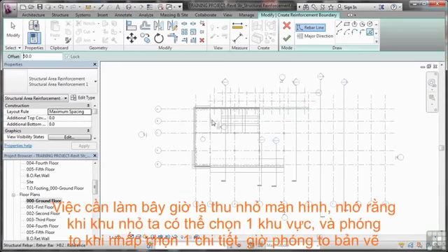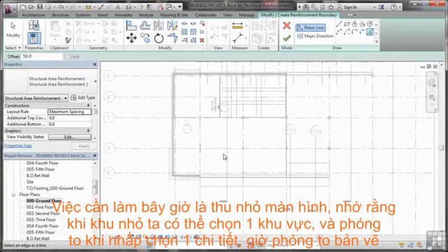So what I've got to do is go to my slab and zoom in. So I need to zoom in now, and you'll notice once I'm in that mode, I can't zoom in or out until I click once in the drawing area. Remember to do that click. Don't be fazed by that. You click in the drawing area and you can zoom in and out.